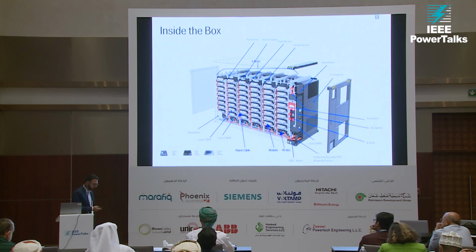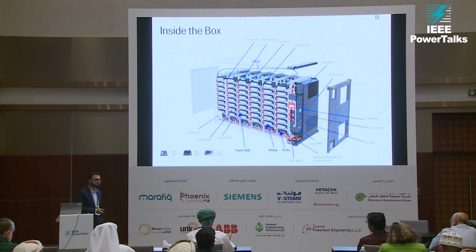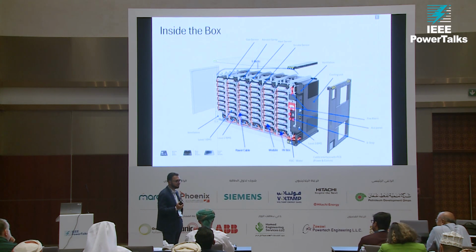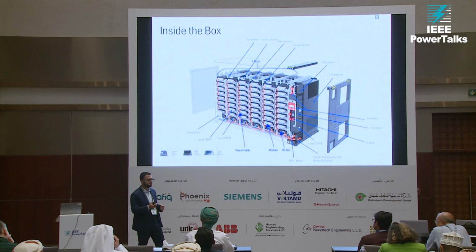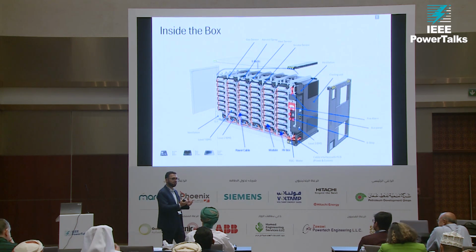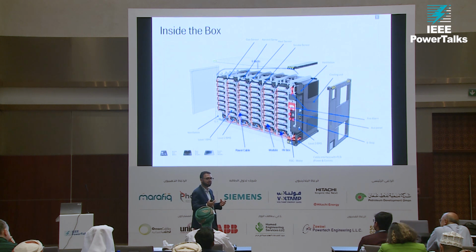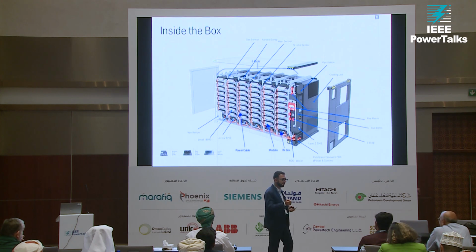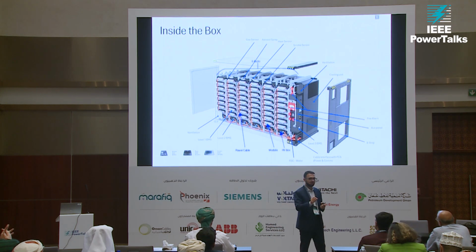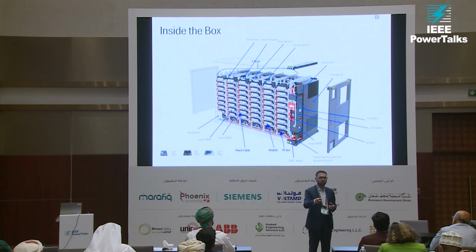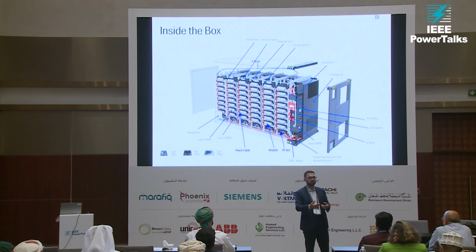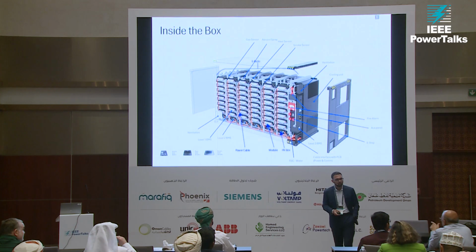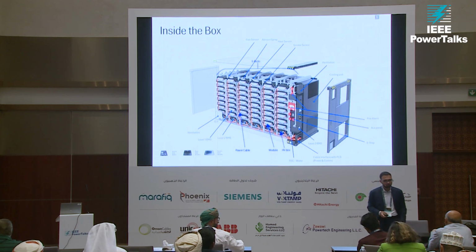Yeah. No problem. Good. What is dendrite formation and how to mitigate it? Dendrite formation is basically this: the electrolyte, as I mentioned, acts like a conductor that helps the flow of electrons, but the separator prevents the cathode and the anode material from contacting each other and shorting. So with a dendrite, what happens is that the electrolyte becomes solid. So it becomes like a wire. And that wire connects your anode and cathode together and short circuits the cell. So that's kind of the mechanism. Yeah. When we are talking of fire, basically there is generation of hydrogen gas inside.